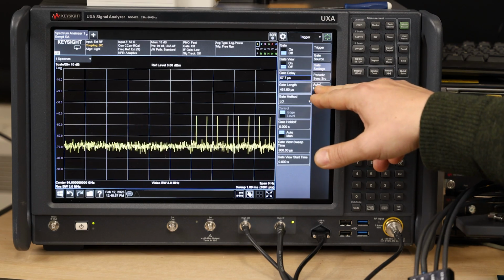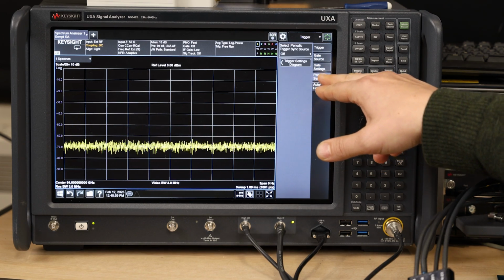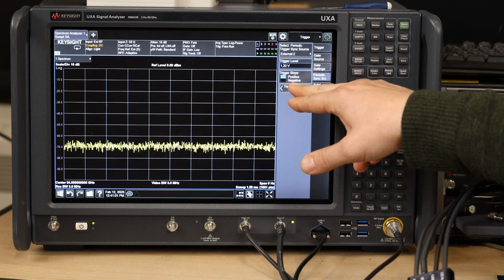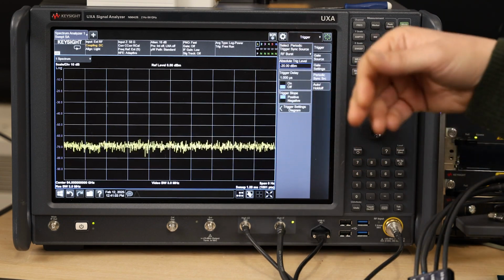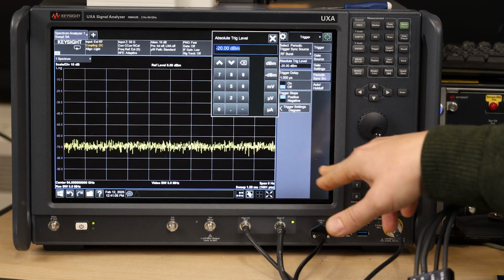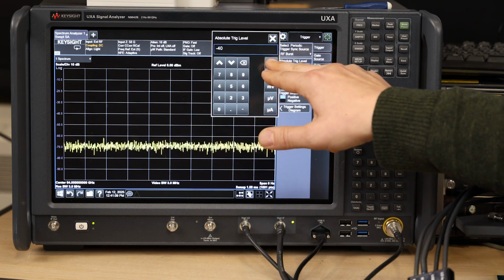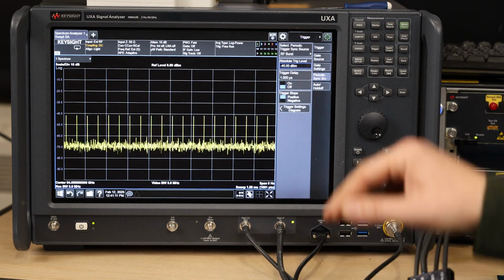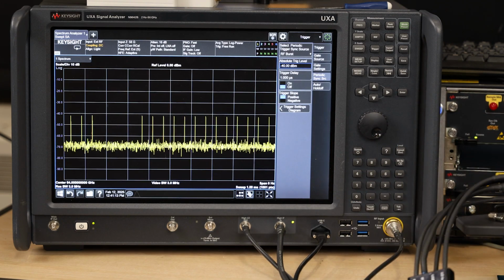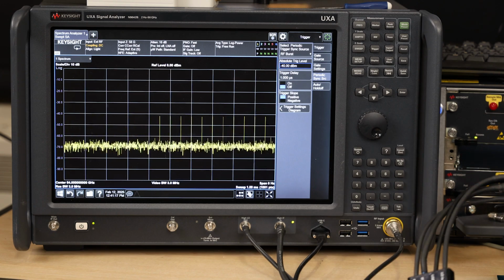And then let's go to our periodic trigger. Let's use the RF burst trigger to train the trigger. Let's choose a trigger level for our RF burst trigger of minus 40 dBm. Our pulse, we're FMCW chirping for over 15 milliseconds, and then we're off for 35 milliseconds.